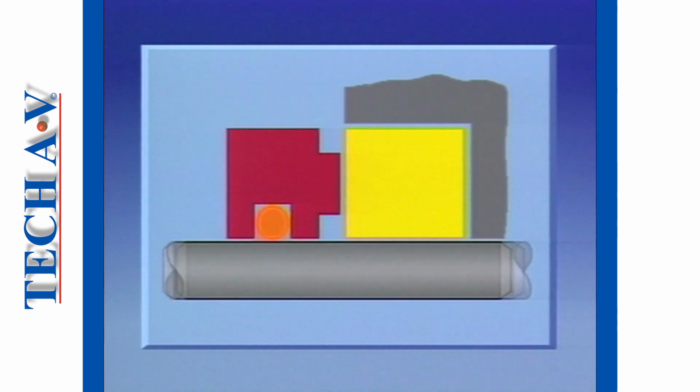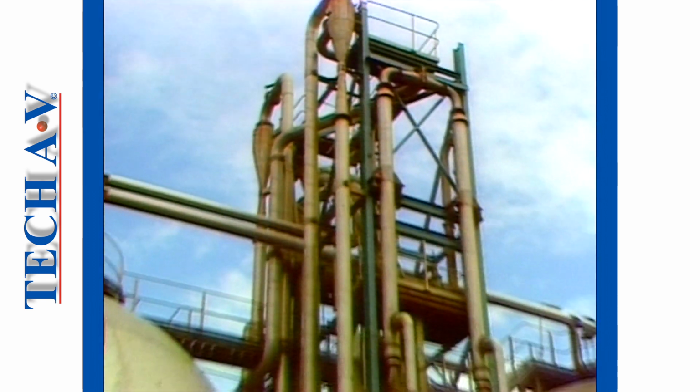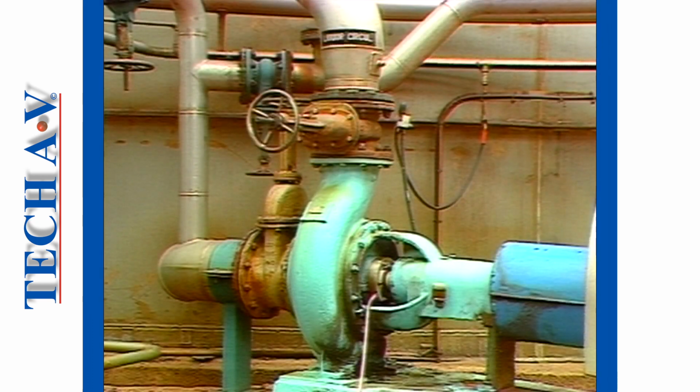However, there is always some amount of axial and lateral shaft movement in any equipment. This results in the eventual wearing of the O-ring, shaft fretting, and subsequent leakage after a period of time. O-ring seals are still popularly used, mainly due to low cost. They are suitable for low to medium temperature operation and in mild chemical conditions.